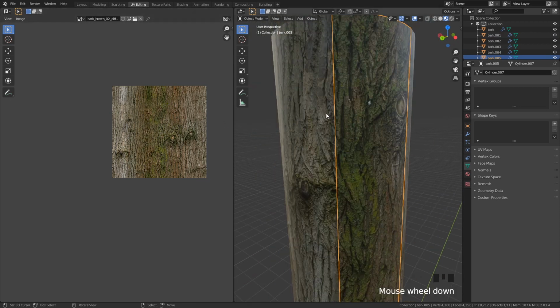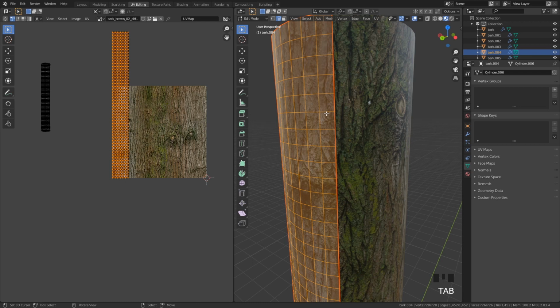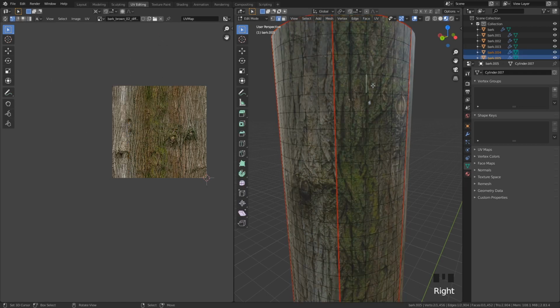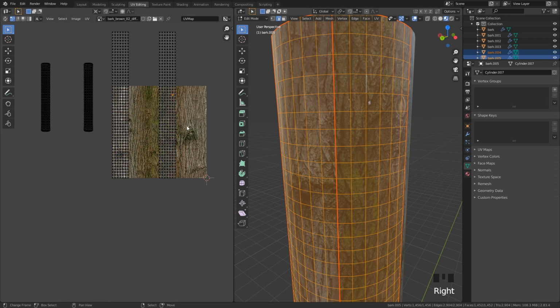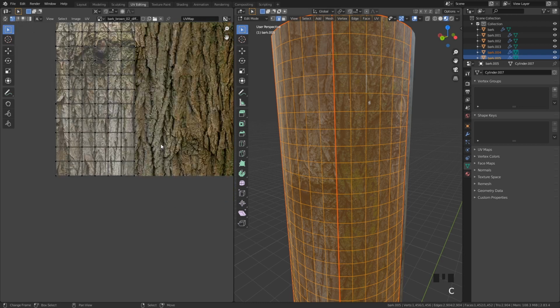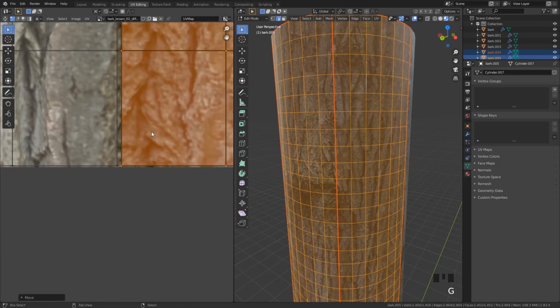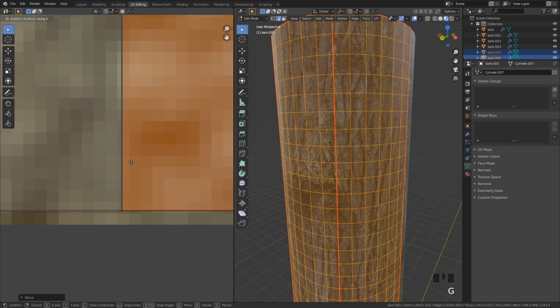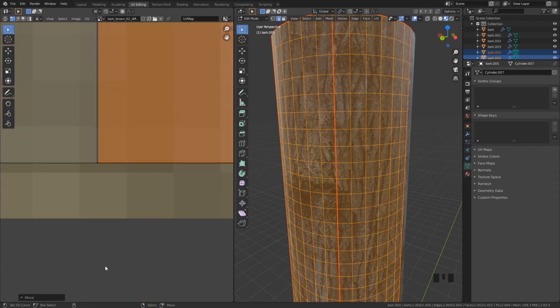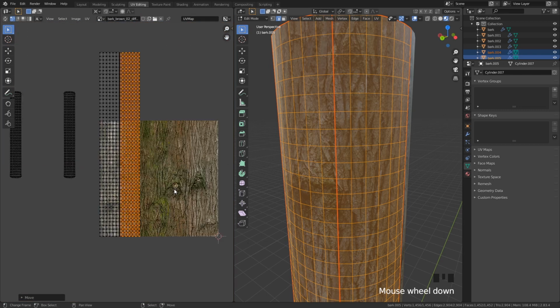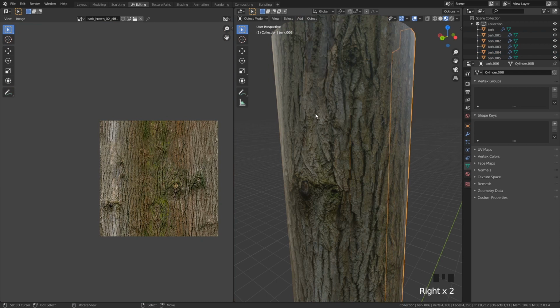Well, this is going to be a little bit annoying, but it is kind of the only way that I found to do this. So what I did is I just selected both these, and then make sure I select the wrong one in the 2D section and just move it to the right. So move it around the x-axis, G X, and then just move it as close to each other as you can. And now these two parts are seamless, as you can see, right?